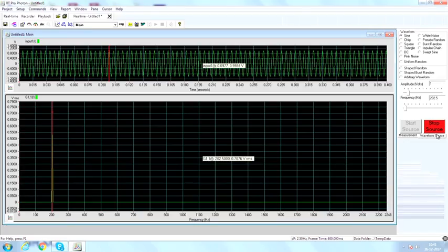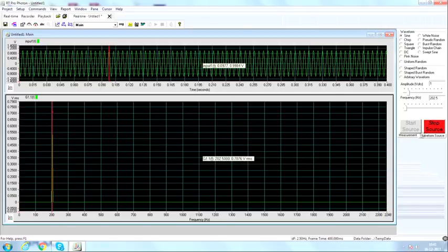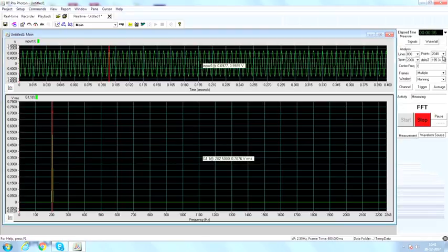We showed you the FFT, the frequency domain, and because this is a single frequency signal, you only saw one frequency. I demonstrated the effect of delta f being small or large, and how by changing the value of n we could change the delta f value.